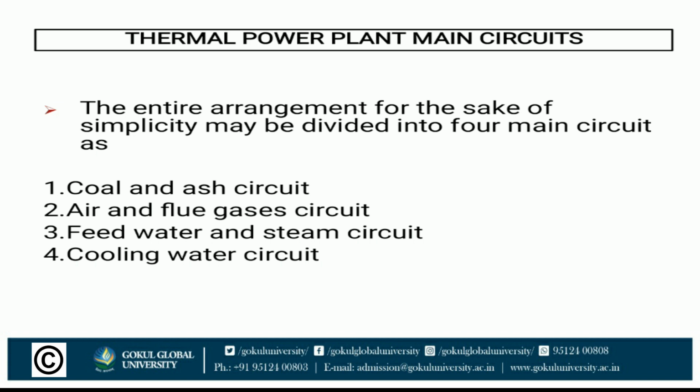The feed water then passes through the deaerator and high pressure feed water heater, where it is heated by the heat from steam which is extracted from the turbine at a suitable point. The deaerator removes the dissolved O2 from the feed water, meaning condensate. Then the feed water is heated in the economizer and fed to the boiler with the help of the feed water pump.